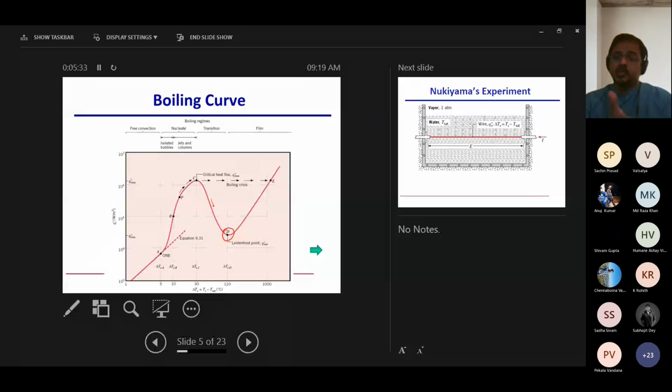And what happens is when he now pours in the batter, which has water inside, the water will boil. But because of this high temperature, as soon as he puts in the batter, which is at room temperature, the temperature of the surface will come down a little bit, but that's okay. You are still heating it, so it will eventually rise again. But there's a tendency for this vapor film to form, which prevents the batter from sticking to the pan.